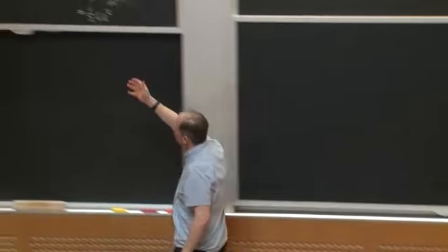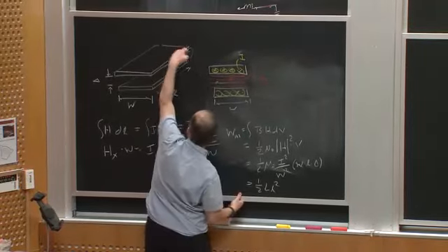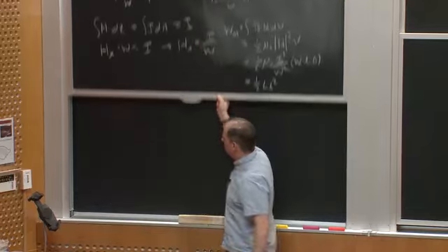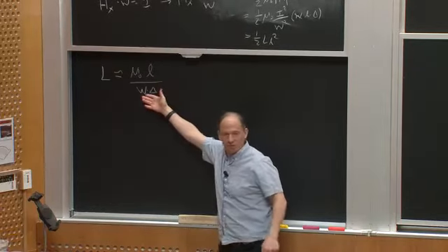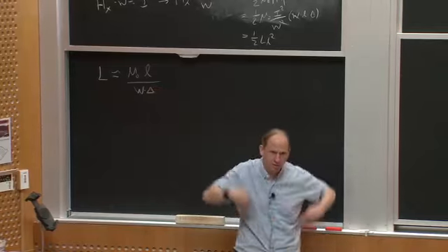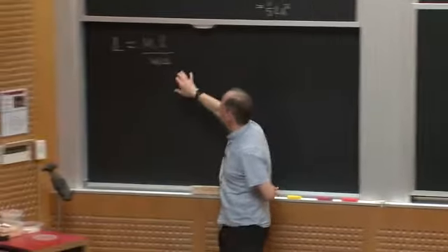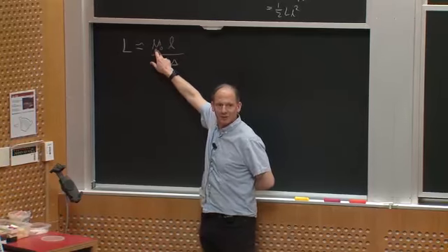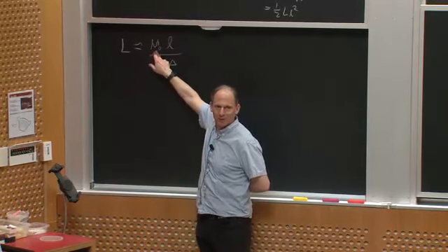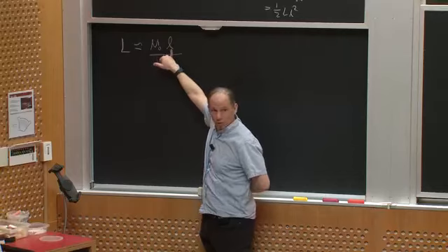Okay? So the inductance of this trace to carry current up and back is going to be basically mu naught L over W delta. So if I want a low inductance loop, what do I want? Firstly, obviously, I'm assuming there's no magnetic material in here. Clearly, I don't want magnetic material in there if I want it to be low inductance. I want it to be short.